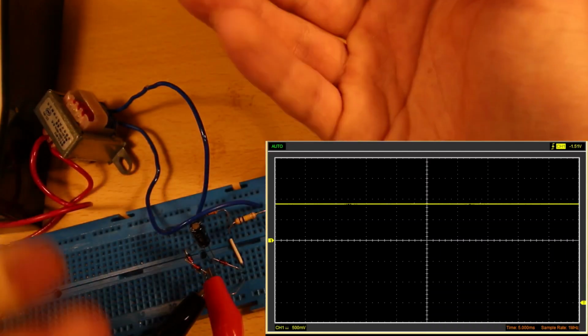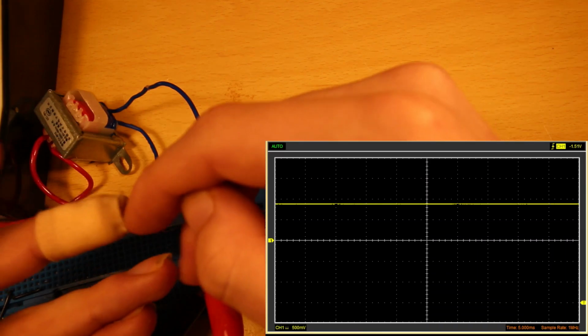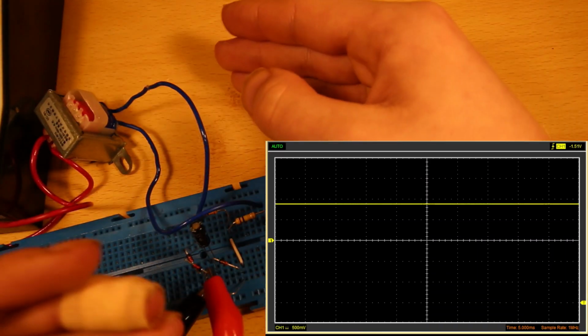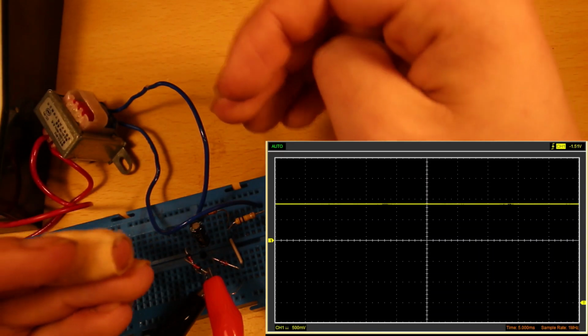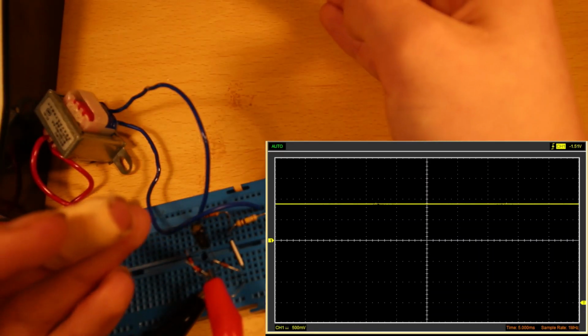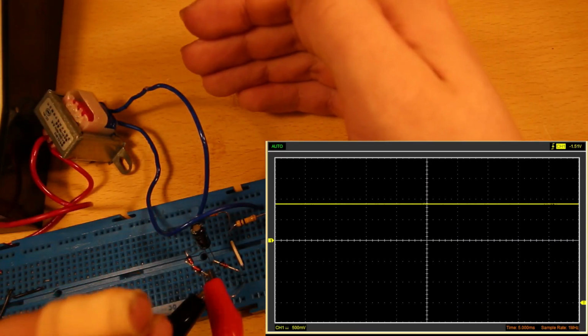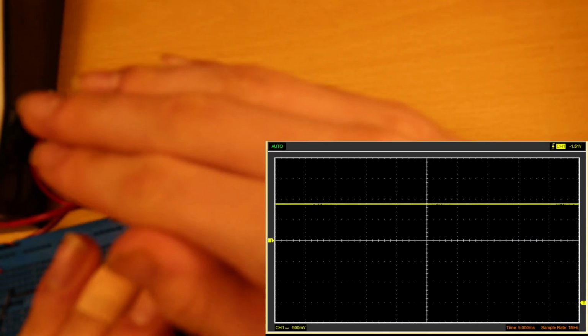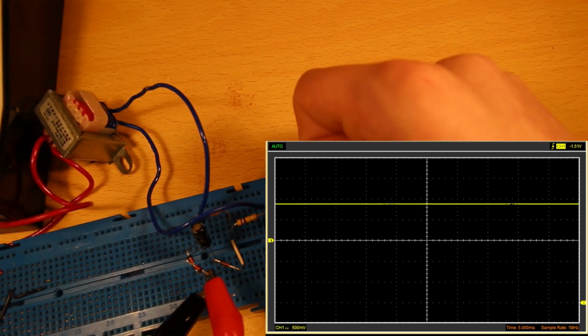You can imagine then how if instead of having one waveform charging the capacitor, we had 3, that would make the capacitor charged even more often. And let's say we had 6 or 12 like you do with the trains, that charged the capacitor even more often, so the output you get is a much more stable voltage the more often you charge the capacitor. That's rectification in a nutshell.